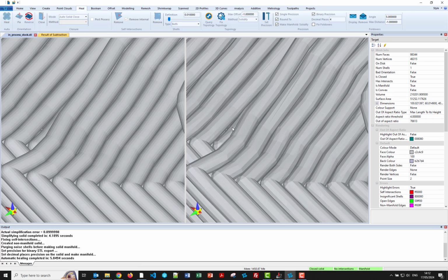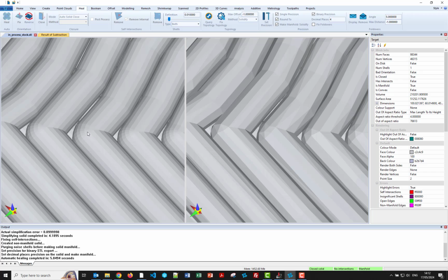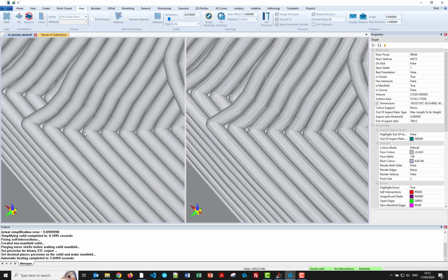And if we zoom in and have a look, you can see MachineWorks. What MachineWorks creates is all controllable using tolerances. You can change the tolerance for every cut if you want to, or every tool motion. Obviously, most people don't. Similarly, you can loosen it for a fast preview or tighten it to get really accurate results, for example if you're doing cutting force analysis or whatever.